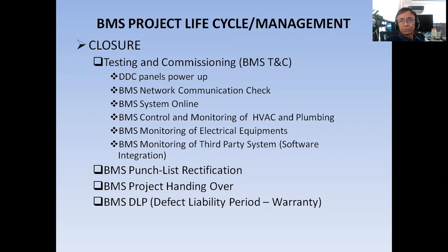Then for monitoring of electrical and other systems, you see if you can monitor the real-time status of those equipment. Then if you have done some software integration, you have to check also BMS monitoring of third-party systems. I already discussed what BMS software integration is in my previous video.